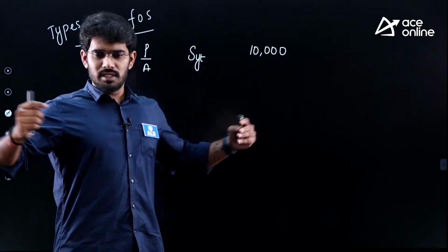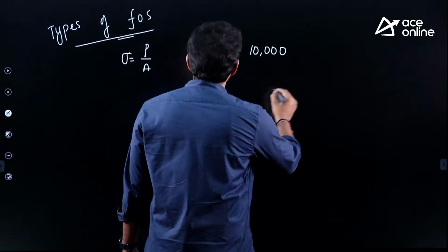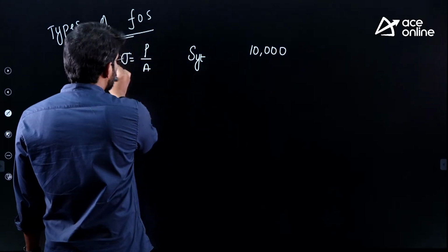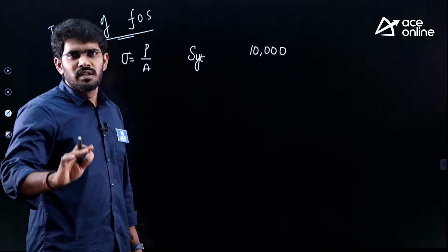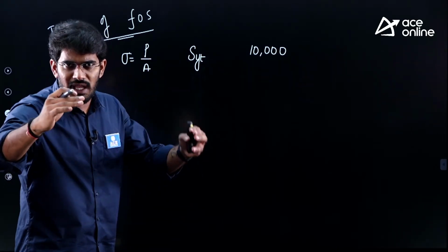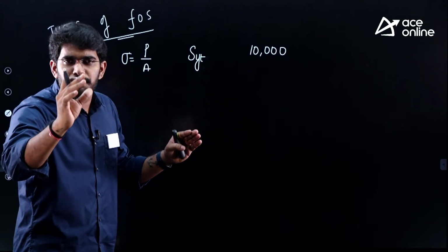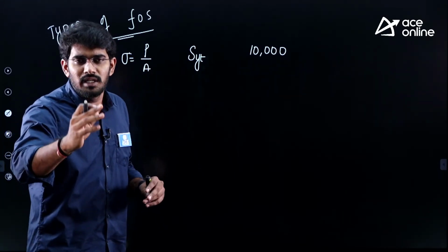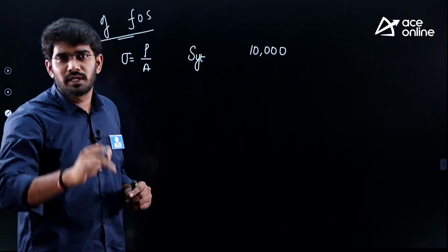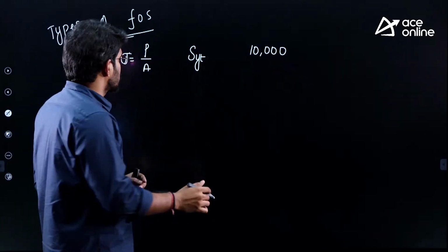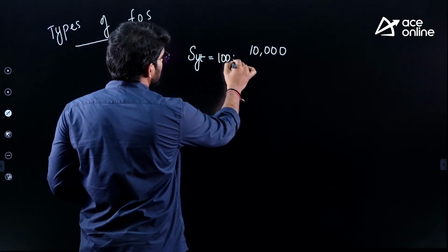If you say, yes, I want more safety, then what he'll do is, as we know that the stress should range from 0 to SYT, he assumes that the stress on this particle of the component is never going to cross a particular value. Suppose SYT value is 100 megapascal.